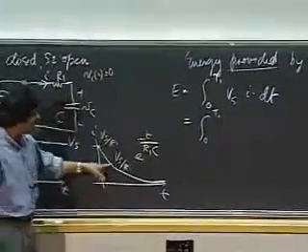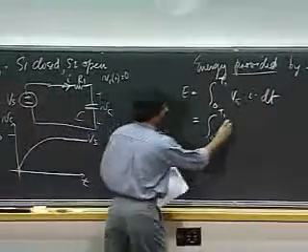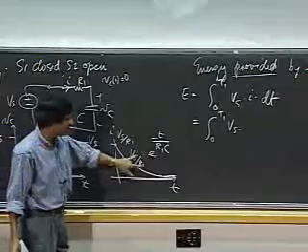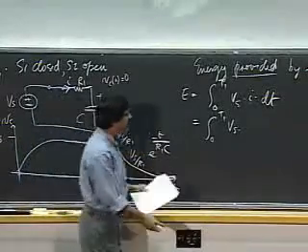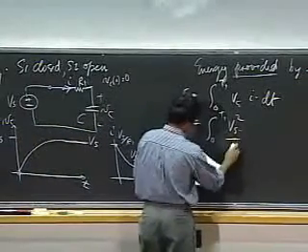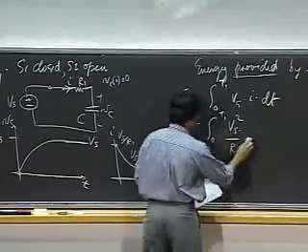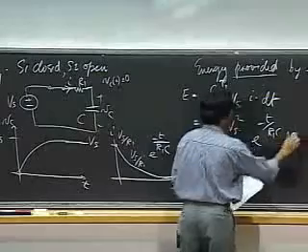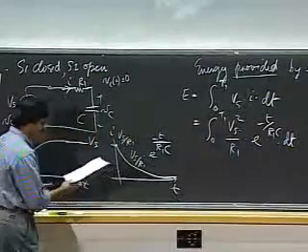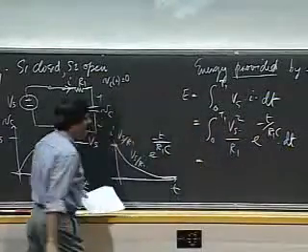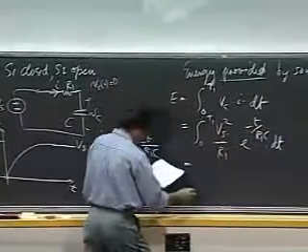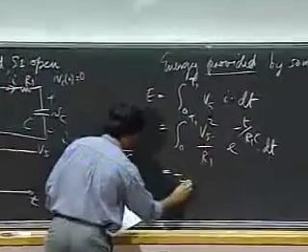So it's Vs times I. And I is Vs divided by R1 times this expression here. So that gives me Vs squared divided by R1, e to the minus t over R1C dt. Let me carry out the integration there.